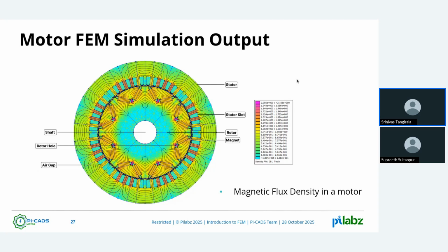As you can see, the magnetic lines, the flux density is very high in the regions close to the magnets, and that is also impacting the magnetic flux inside the stator. And this is a very uniformly distributed magnetic field. This is what will give an indication of how powerful the motor will be, the intensity of the magnetic field and the geometry and everything put together. Because the geometry will dictate how big or small the motor is.